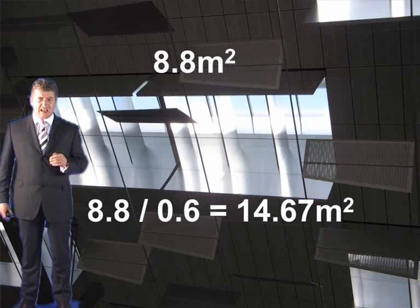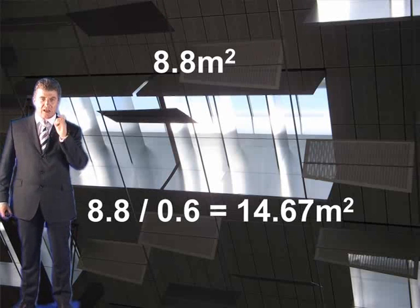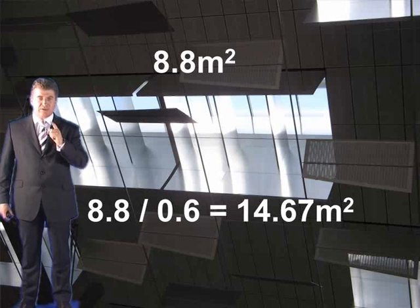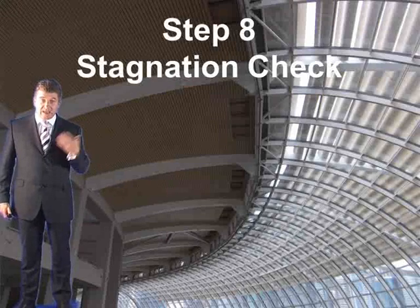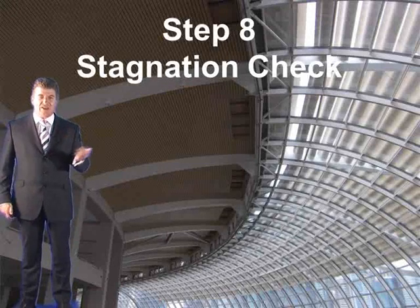And don't forget, ventilators don't come bigger than 6.25 metres squared, so we need at least 14.67 divided by 6.25, which gives you 2.347, or 3 ventilators. That's what you'll need, at least 3 ventilators, the absolute minimum. So where do we locate this? Well, before you can decide where you locate them, you've just got to carry out a stagnation check.